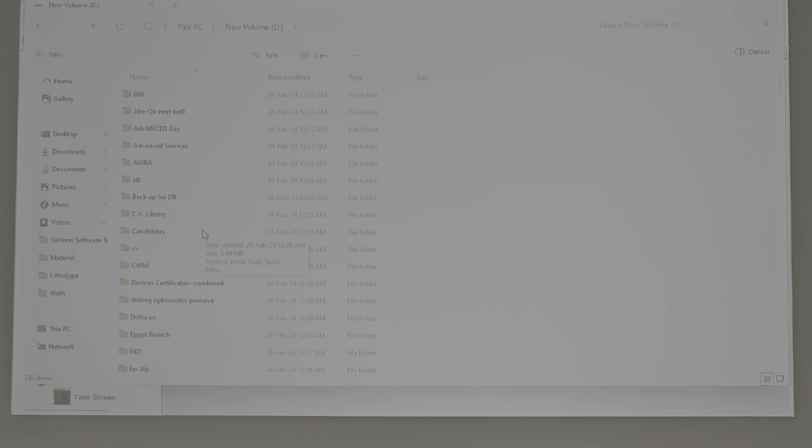So you cannot make a well control evaluation unless you have SCR. Why is this SCR important? Because it's a kind of calibration, a kind of reference. It means that in normal condition, 30 strokes gives 50 bar.